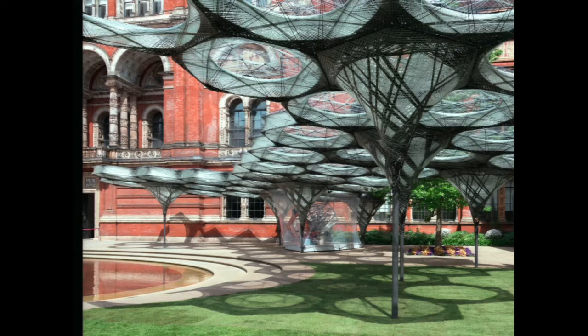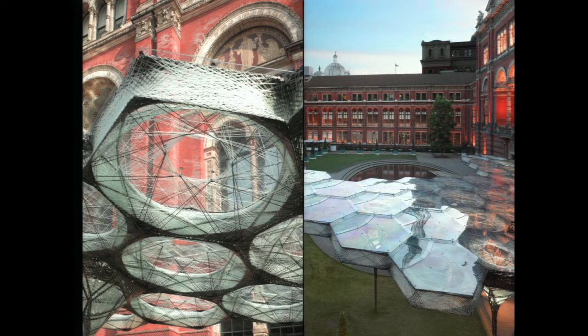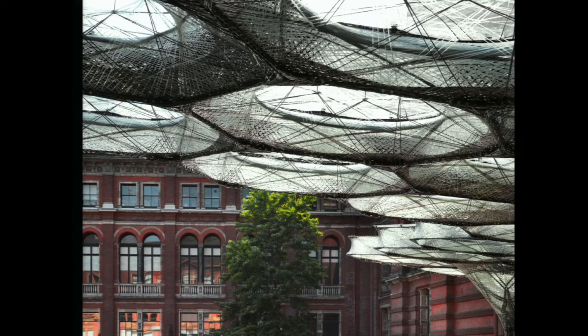And I think the other aspect is that it really was, for us, the first indication of what a fibrous tectonic in architecture could be, because I need to remind you that the only load-bearing material in that roof, which has about 225 square meters, is carbon and glass fiber. There's no steel, no nothing. It's just fibers. And that, in return, means that it's an incredibly lightweight structure. So the entire roof weighs about 2 tons, which is the same as 2 square meters of the brick wall of the VNA. So it is really a different dimension of lightweightness.